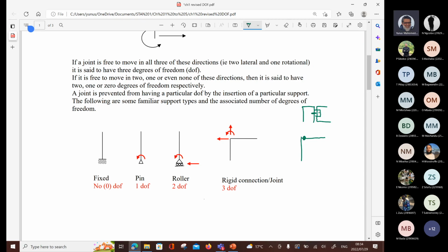So remember when you had something like this in analysis? You had a pin support there and you had a pin support there. It was statically indeterminate, right? Okay, so to make it determinate, what happened? You introduced a hinge. Okay, so that's what I'm talking about now. Can it still move horizontally? Actually, it still has the 3 degrees of freedom.